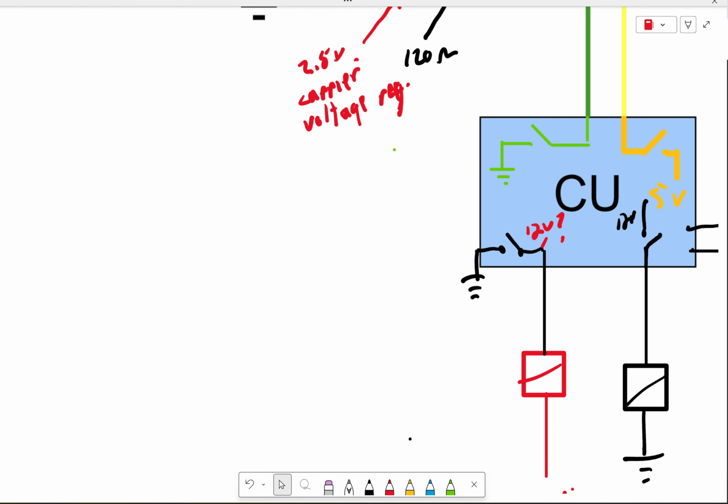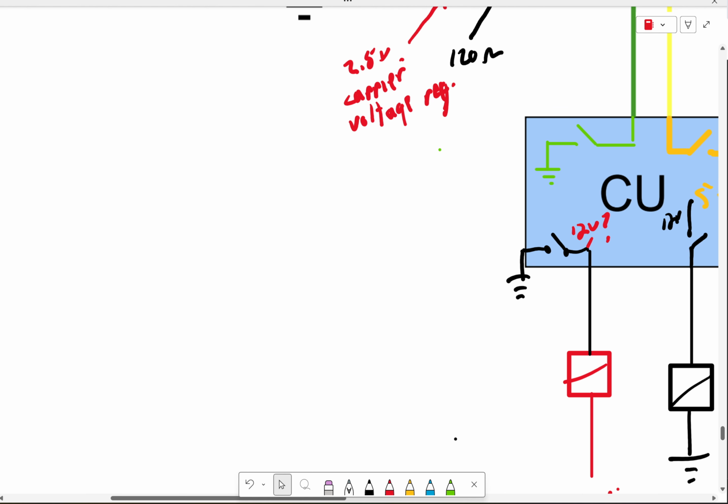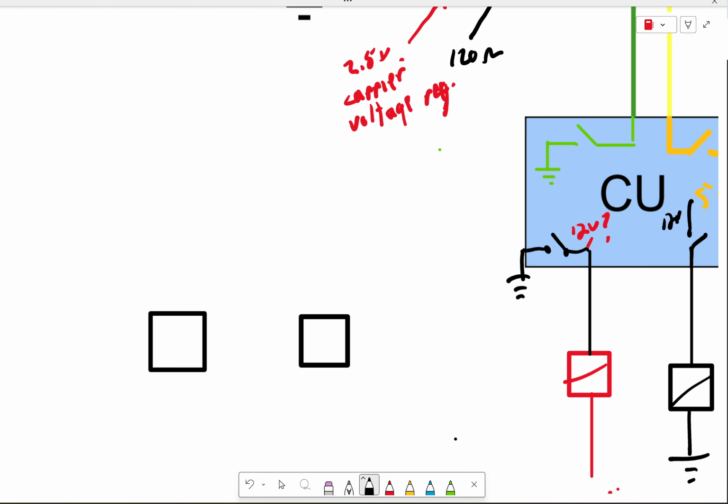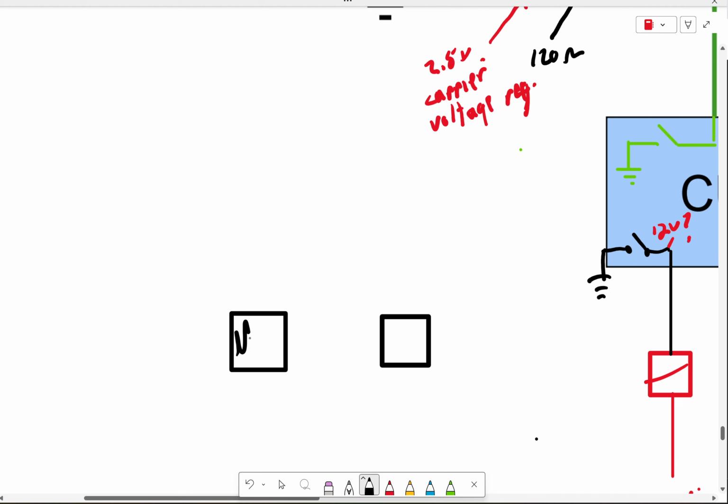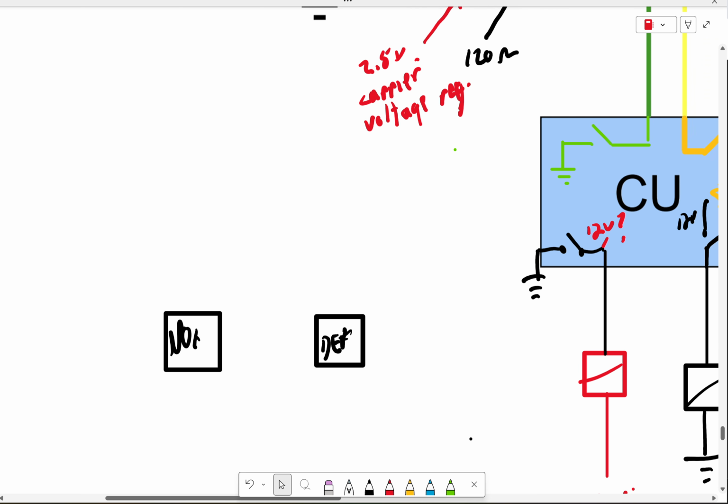So that secondary CAN bus, let's go ahead and add that to this controller that we're kind of fleshing out here. We'll give ourselves 2 extra control units, okay? And if this was an engine controller, one of these might be a NOx sensor, one might be my DEF pump or something like that, or my DEF module, I guess we should say.